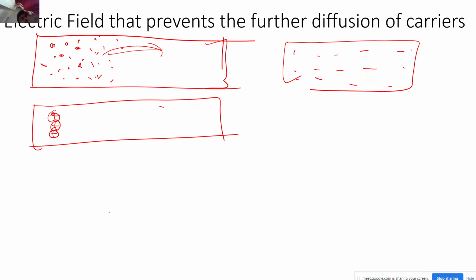One of the answers was biasing. Kushagra said that. Okay, but with biasing, I can inject excess electrons, right? If you take a simple N-type semiconductor, then no, because the moment you inject on one side, it's like some resistivity. You can't have accumulation of charges anywhere. It has to flow out of the circuit. But if you have a PN junction, of course, you can have certain regions where you are injecting and so on. Yeah, that happens.